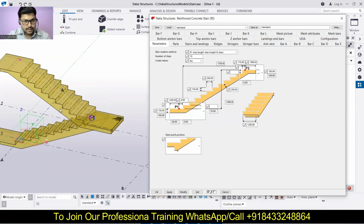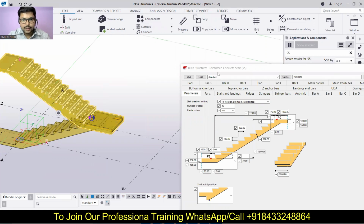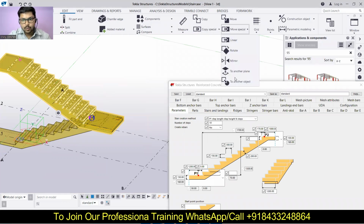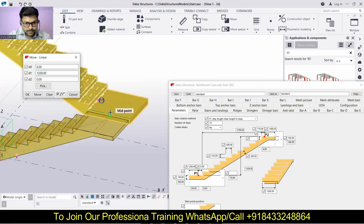Okay, now I have to select this staircase over here, and I will have to move it. Let's click on Apply also so that it is applied. And then I have to simply move this. So for that I'm going to check the direction. So this is X direction, this is Y direction. I will have to move it in a linear way in Y direction. So I will go for Linear, and dy I have to move it by 1200. So click on Move.